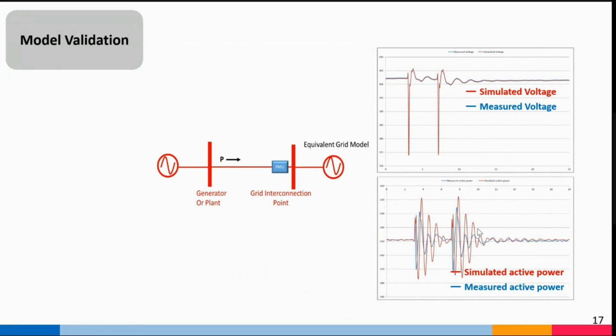So you have to properly model your excitation and properly model your governor. There are certain software packages through which you do this modeling, and by putting in the models and the parameters from the field for that particular plant, you need to check the system performance, whether the dynamic behavior of the system for any event is matching with the actual event or not.